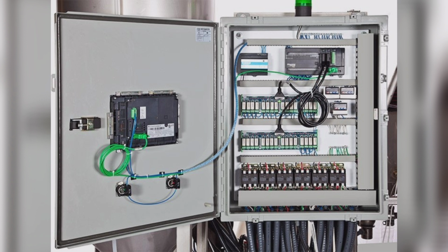This means that on the control panel, a handle is provided so that we cannot open the door physically. Instead, we can only rotate the handle in order to shut off the system, in emergency cases as well. Always remember the top side of the circuit breaker will still have power. The power that comes into the panel can be anywhere from 480 volts down to 120 or 230 volts.